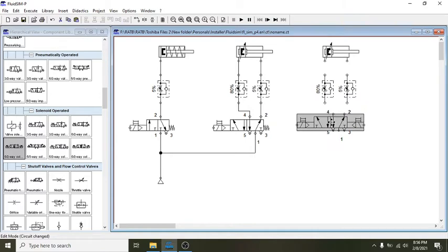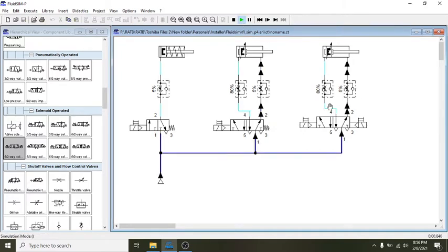You can see there are two coils now. We connect the shut-off valves, then connect the other end to the solenoid valve, and then the source will be connected to the compressor. So we try to simulate, now using the double coil 5-2-way solenoid valve.